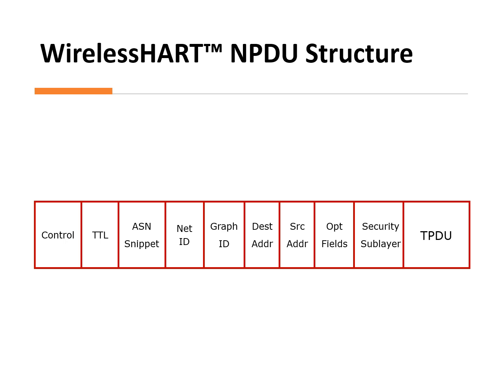A security sublayer field consisting of a 1-byte control field, a 1-byte counter, and a 1-byte message integrity code, MIC. The control field specifies the type of security employed. The security type and the counter field are used by the application security algorithm. The MIC field is used to check the data integrity. And an encrypted transport layer PDU, which encapsulates the APDU.